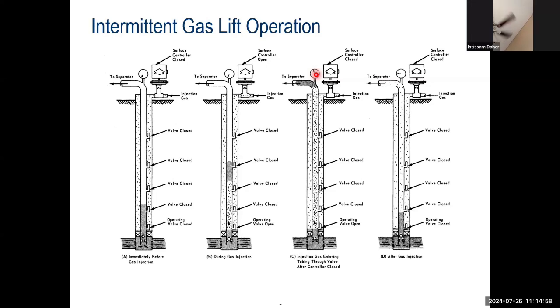Yes. You can use nitrogen, you can use methane, you can use a mixture of the gases as well. And a second question: what should be the temperature of gas when we use these accessories? The gas lift system is rated to, including the seals, a normal system can be rated to 200 to 250 degrees Celsius. But yeah, that is the normal temperature.